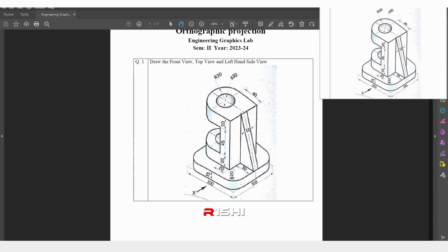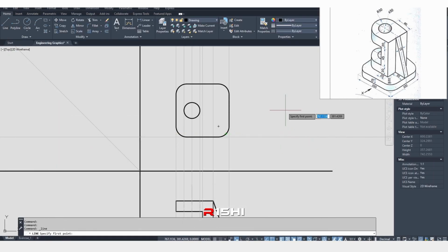So we are going to locate that using from command in AutoCAD. So you start the line command when AutoCAD will ask you to specify the first point. We don't know where to click directly. So we will say I want to use from command. So FROM, enter, and use this corner. Okay, you can see this is the projection. So this is the corner we want.